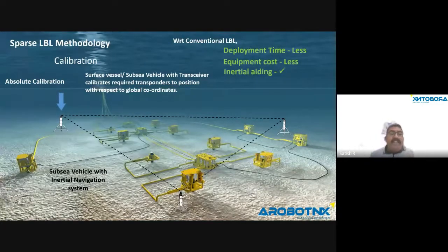There is also a way of carrying out references, like getting two solid reference LBL transponders talking with that INS and carrying out an absolute calibration. That's also possible. There's a methodology to carry it out in 2D. Like I said, 2D and 3D are different. In 3D you have to consider the depth and the height, whereas 2D is just the position. So whenever you carry out any kind of operation, these things are to be considered to the core.